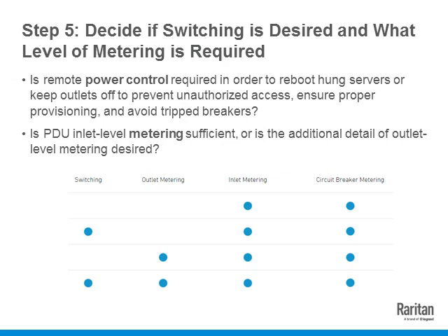Another benefit of circuit breaker monitoring would be to place thresholds on these. So if there is one circuit that's drawing a lot more power than you anticipated, let's say 80% of the breaker's value. In the United States, we have breakers rated at 20 amps at 100%. So if the power draw is going higher than 16 amps on one branch circuit, then most likely something is going to go wrong, and it may make the breaker trip.